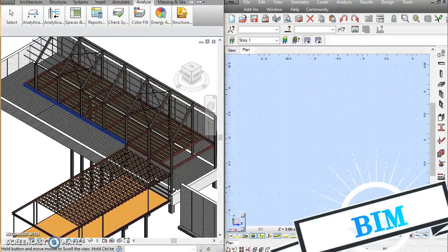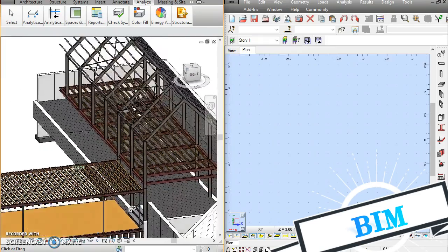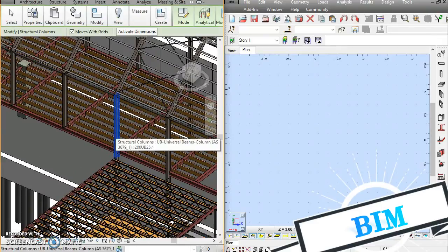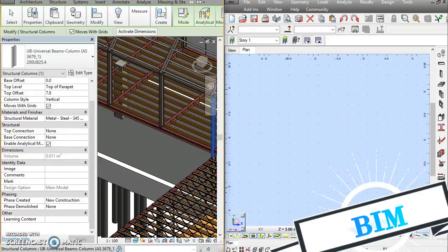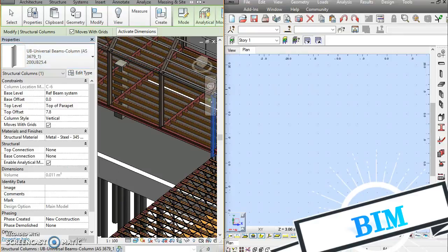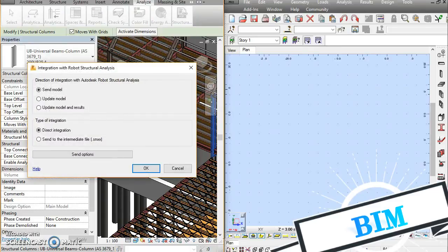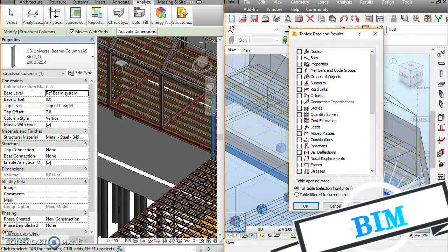From the design drawn in Revit as a 2D or 3D model, we have the opportunity to isolate all the architectural parts in Revit and keep the structural parts for the investigation of the building's features. In order to export the files into the Robot Structural Analysis, we use the Robot link in Revit called Structural Analysis Link. Once the link is exported to Robot, we can investigate each member in detail, make changes, and find information about the structural parts.